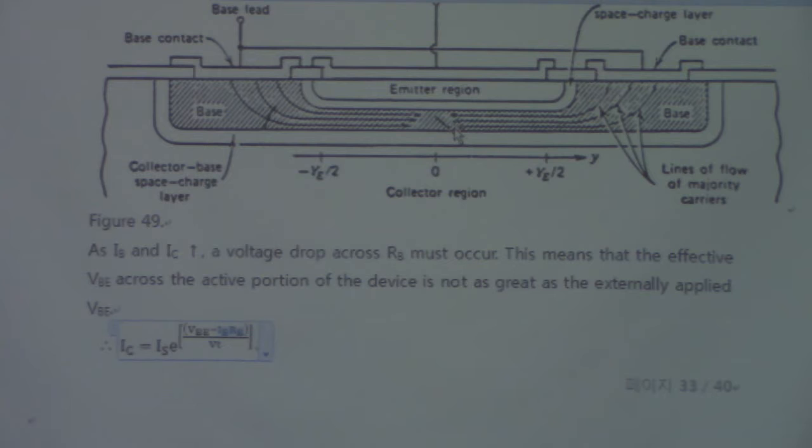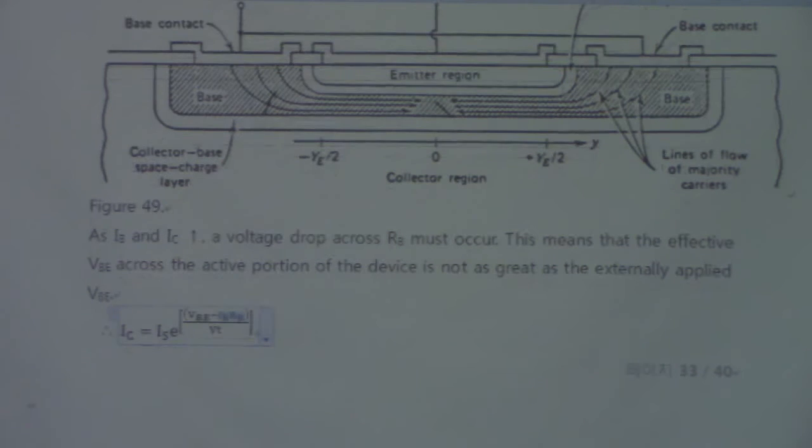But as you see in the Gummel number, which is exactly the total amount of the dopant in the base, you have to have a low base concentration of the dopants to increase the beta values. So this has to be optimized in some sense if your device is working at high voltages.